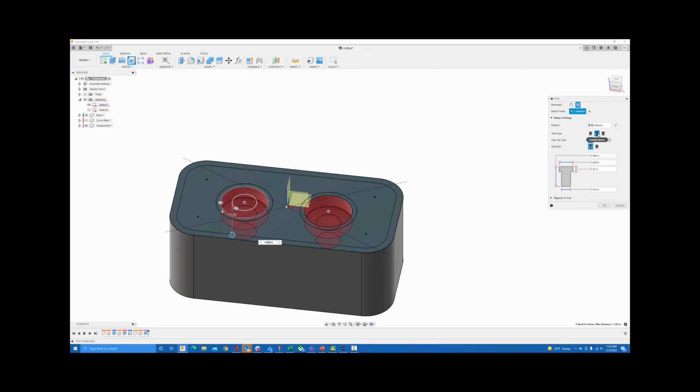All right. So we want to do a counterbore here, and I'll drag out the bigger diameter, a little bit bigger than the circle. Actually, we'll just kind of do a press fit. So we'll do something like 1.05. And we'll come down that depth there, we'll do 0.125, and then that outer one we'll make a little bit bigger, something like 0.9.